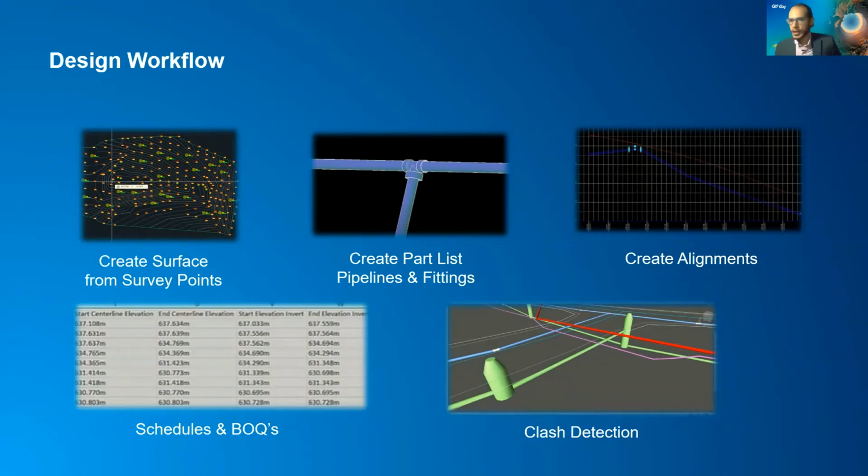So if we have a water utility or a sewer utility, whatever the type of utility we deal with, we need this information, because it will affect the shape of the alignment or the profile of the pipeline. It will help us to define what type of control structure, maybe to increase the level of the fluid that moves inside the pipeline, or maybe to decrease it. So we need this type of information.